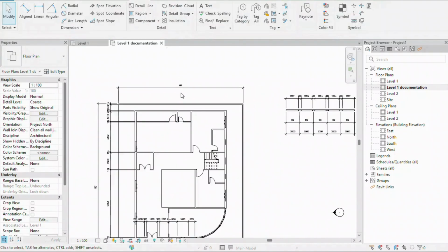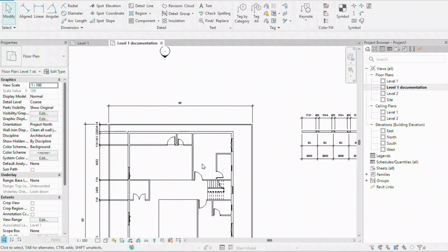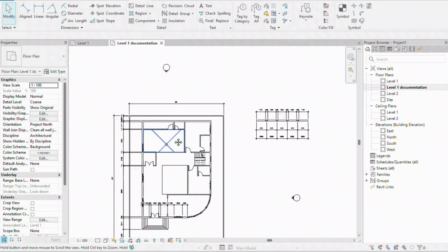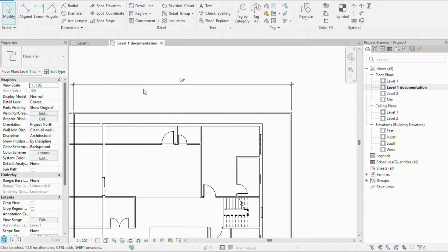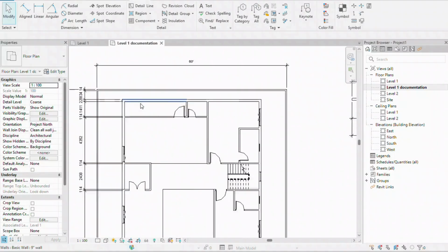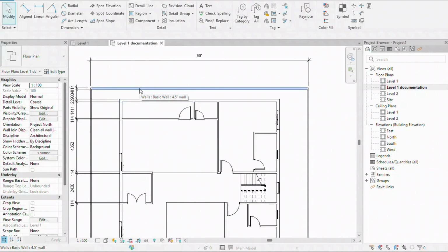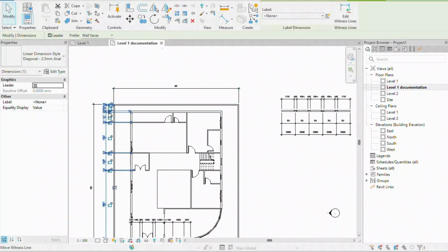Right, now you can see that it is in feet, though the template is in mm by default. Template unit is mm, or the project unit is millimeters by default. I can change the particular dimension units here. Okay, and I can also give the color code for these lines, because the drawing lines are in black color, and if I want to differentiate these dimension lines from the drawing lines, I have to select this.